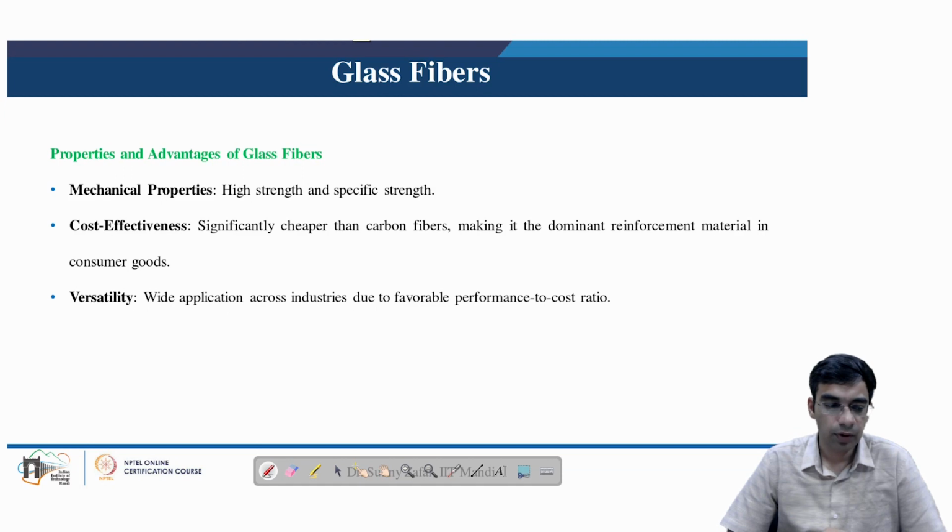If we see the various properties and advantages of glass fibers, these include high specific strength and stiffness. In general, they have high strength. They are also very cost effective, because the manufacturing process as well as the raw materials are of relatively low cost, making them a dominant reinforcement in several consumer goods as well as lightweight high strength products like wind turbines. Because of their versatility, glass fibers also find very favorable industrial applications where the performance to cost ratio is of significance.